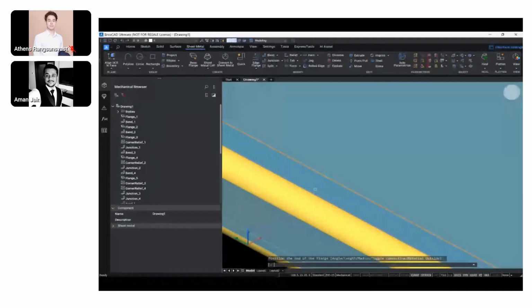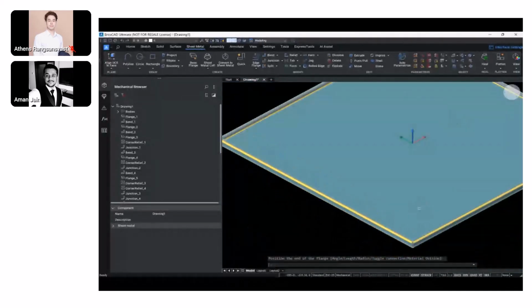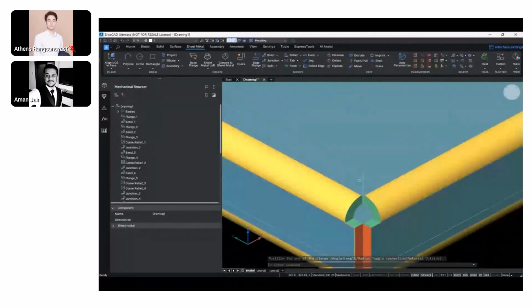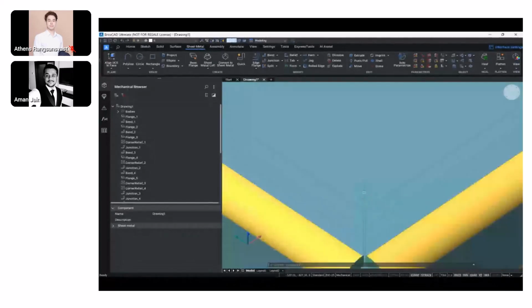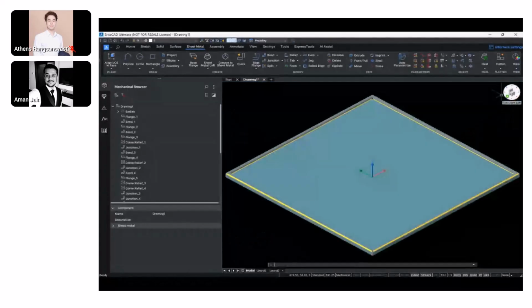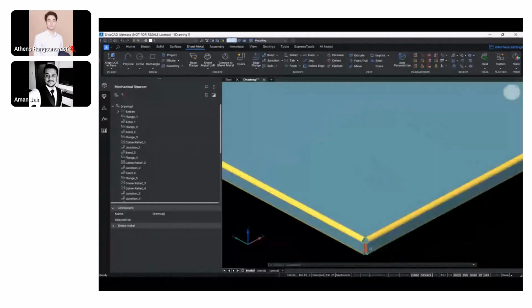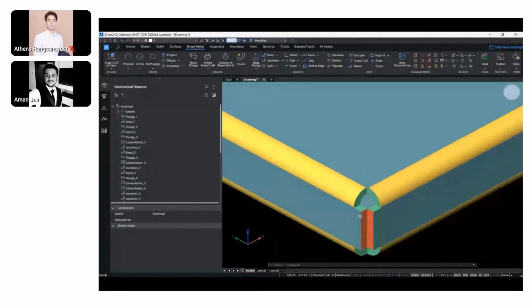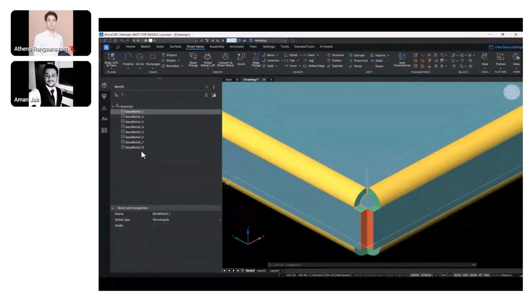Now with this, on the left-hand side, we see the corner reliefs and the miter flanges have been automatically created. The miter reliefs have automatically been created. At the same time, if I want to change the type of bend relief, because for a sheet metal enclosure we need to make sure it's as packed as possible so as to avoid leakages of any kind.